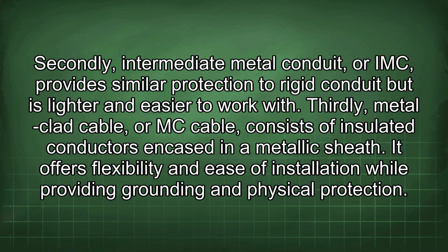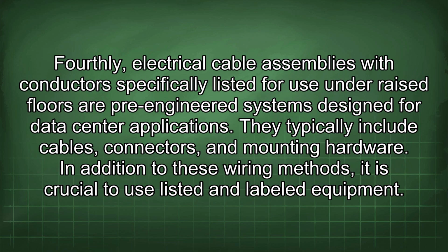Thirdly, metal-clad cable, or MC cable, consists of insulated conductors encased in a metallic sheath. It offers flexibility and ease of installation while providing grounding and physical protection. Fourthly, electrical cable assemblies with conductors specifically listed for use under raised floors are pre-engineered systems designed for data center applications. They typically include cables, connectors, and mounting hardware.